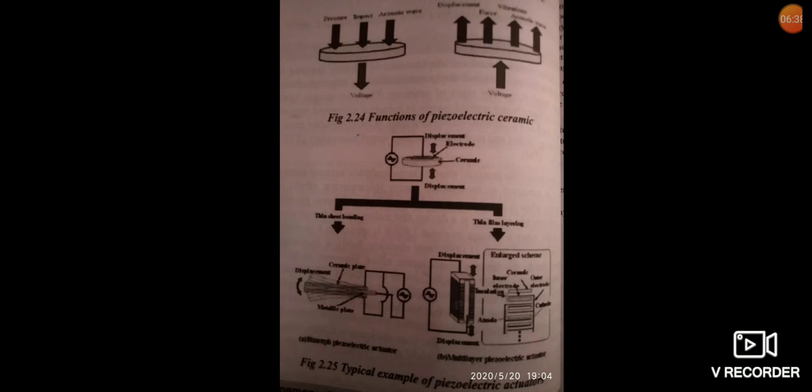Now, when an inverse voltage is applied to two piezoelectric plates, warp deformation is the consequence. The arrangement can offer relatively large displacements, but the force is not large. This device is implemented in a cantilever construction for use in positioning mechanisms, etc. And the driver voltage is usually some hundreds of volts.